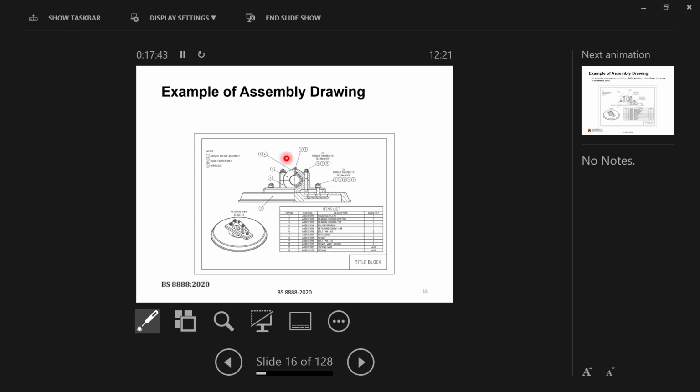Here the assembly drawing is in the middle. Here you have a bill of material. Again, you have all the item parts, and you have these balloons so that you can relate. For example, number one here is the mounting plate, the quantity is 1, and this is the part number. So you can relate what is written here on the bill of material to what is on the drawings. You have the title block. It's not completed here, but we'll see how to create this one. You have some notes as well.